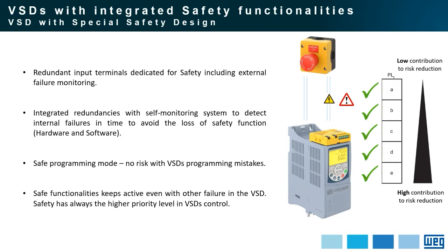It means the same thing that external safety relays will do, the variable speed drive also is capable of doing, checking if the cables between the variable speed drive and external safety components are healthy.